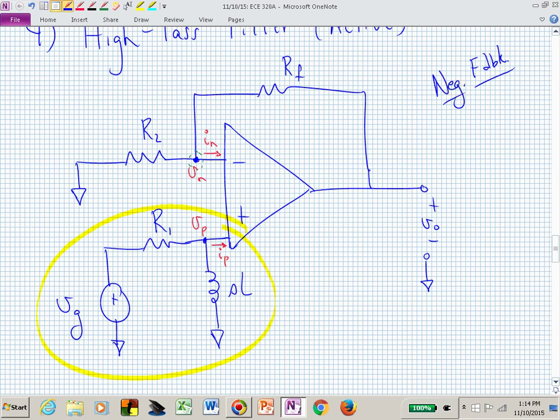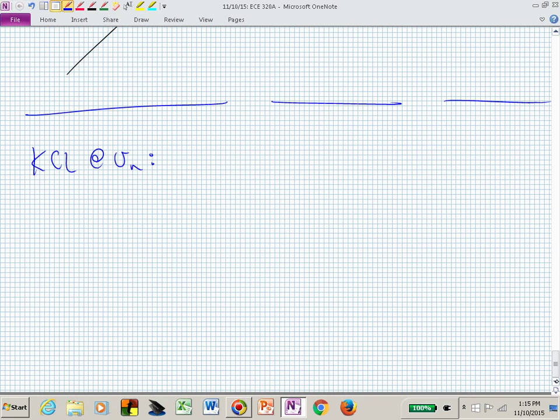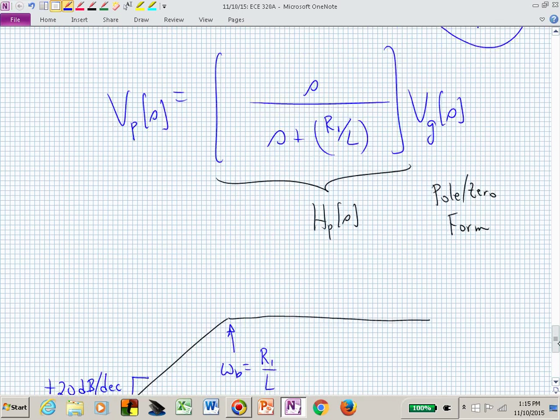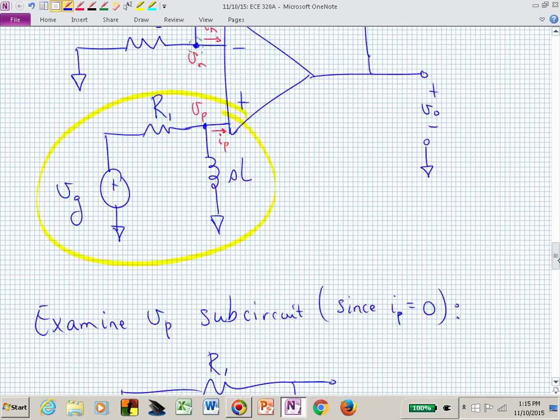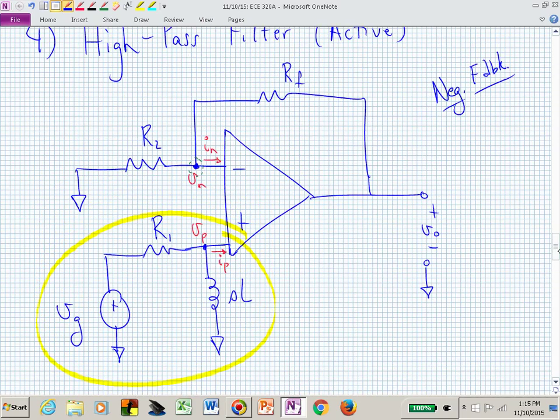It's the voltage dropped across R2, which is V sub n on the right minus 0 on the left, divided by R sub 2. That's the current going to the left. I now can say that's Vn minus 0 over R sub 2. What's going into the inverting terminal? What's going right horizontally?